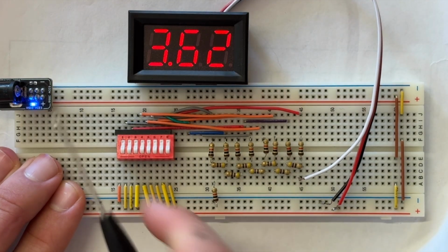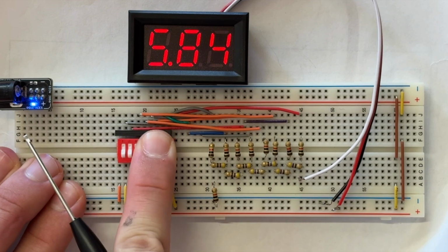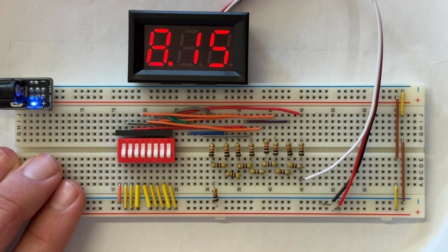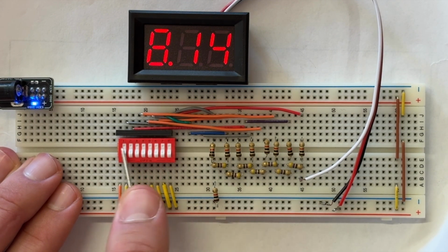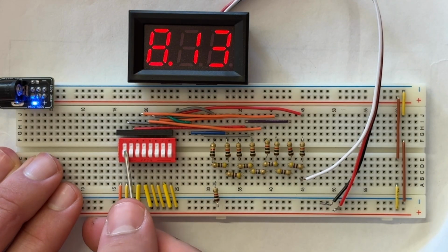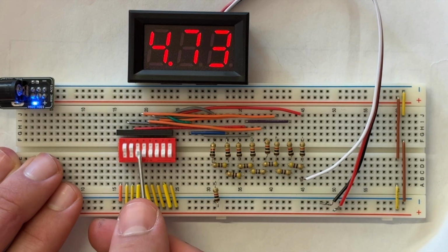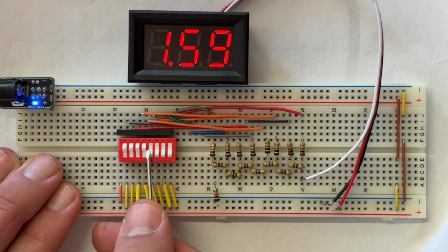Each resistor pair divides the voltage in half, so every bit contributes a fraction of the total output, as talked about in the previous section. The R2R ladder takes these digital inputs and converts them into a single analog voltage. The voltmeter is connected to the V out, as shown in the schematic earlier in the video.